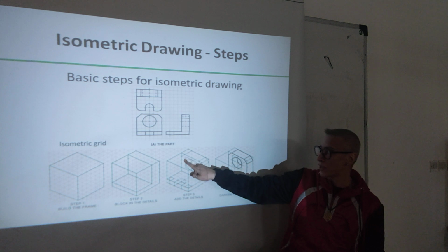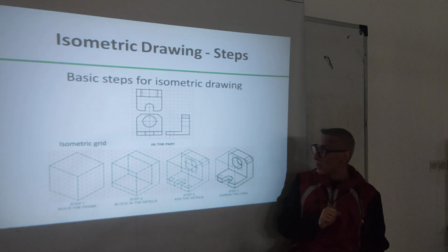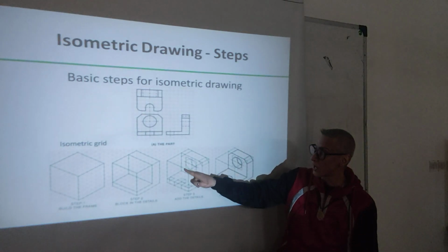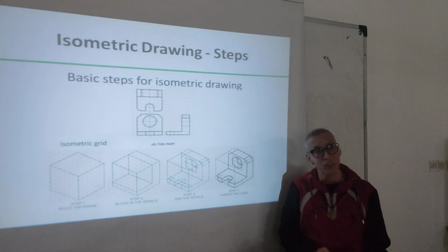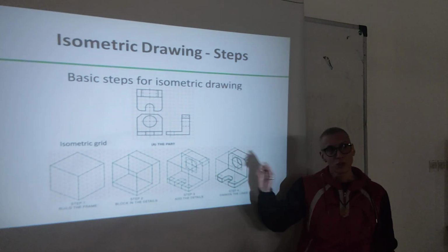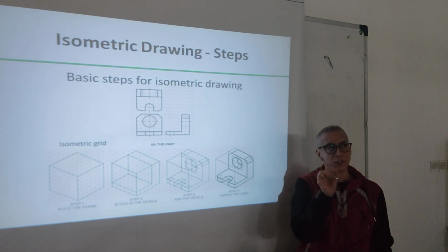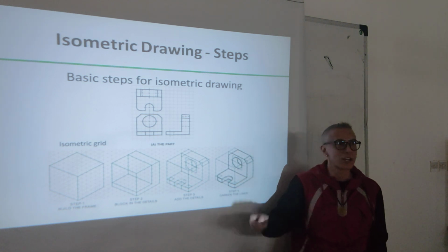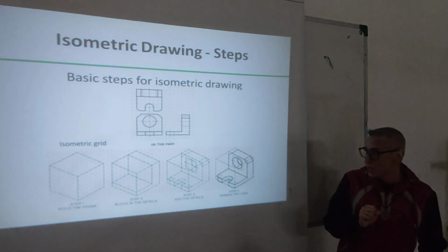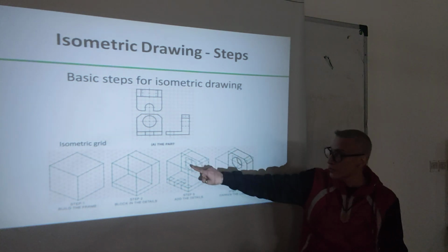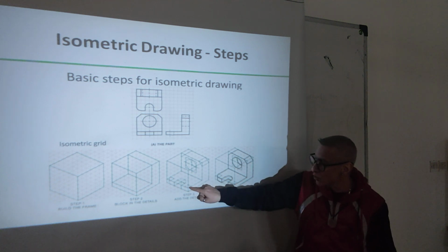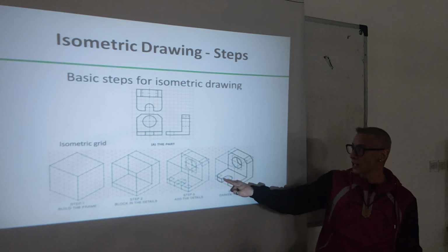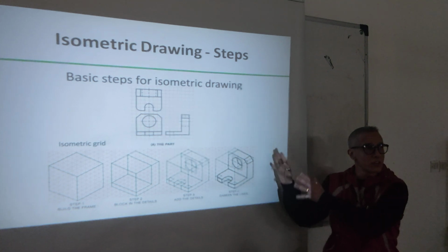Also the circles. If you have circles, you already know how to start a circle. You have to start with a square, okay? So the square has to be drawn first, again straight lines, and then the circle inside. Today we will also cover precise steps in drawing the circle as an engineering drawing, not like in the past, a little bit freehand. But it still remains the same rule that you start with a square, and all of these smaller details are added after. Then in the end, you just darken the object lines, refine details, and that's it.